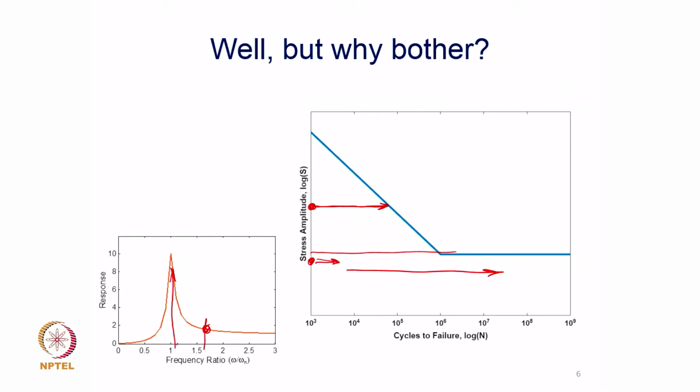Even if you design this element or any mechanical equipment for a certain finite life, calculating that based on your traditional machine element design, where the stress level induced is so much and you expect the life to be this much, and that in your application is probably enough. But if you are not aware and your design is not robust enough, then any closeness or proximity to this resonance phenomena will amplify the stress level much higher, and then you will have a finite, curtailed life.